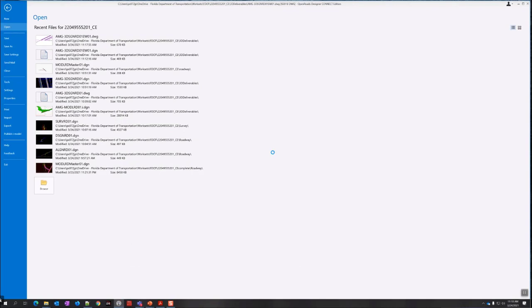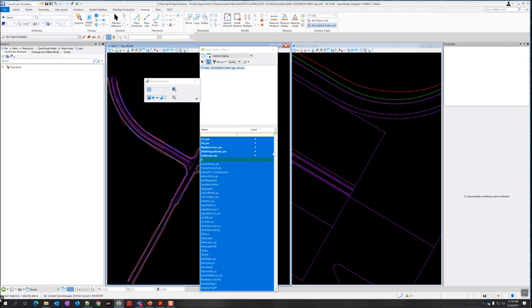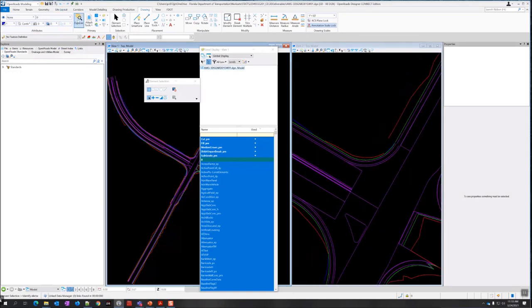The DWG work mode, we found it works better for editing the 3D lines. That was something that we saw with the old versions, PowerGEOPAK, SS4, SS10. You may find that it's not necessary, that you can just edit directly in DGN. We just haven't tested it extensively yet. So that's something that if you want to play with, you're welcome to, instead of creating the DWG. But if you have issues with trying to edit the lines, maybe going to DWG work mode may solve the problem.